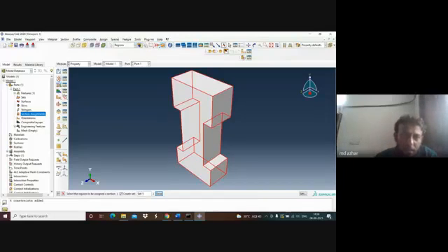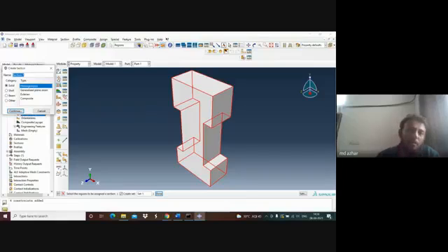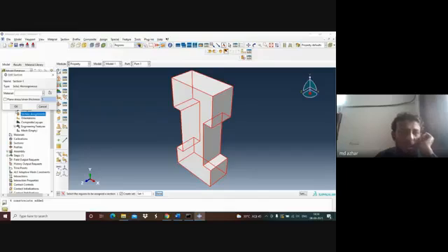but the fillet I have not given, just to make you know what it is, right? So now you create the section, because now you have created the object in the space, but the software will not know what you have created. So you'll create the section, and on creating the section, you will have the homogeneous solid, because we have done it as a part of solid. So you'll have the homogeneous solid and you will continue. So now the software knows.